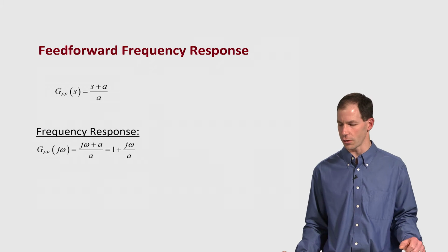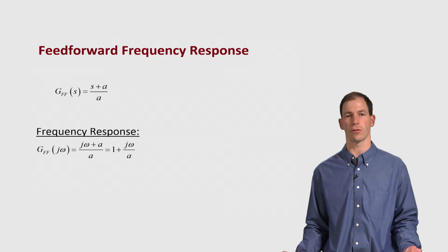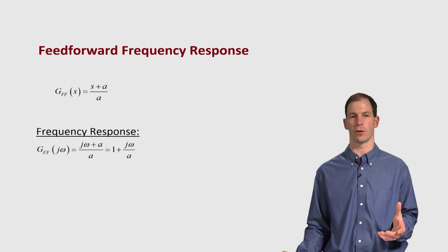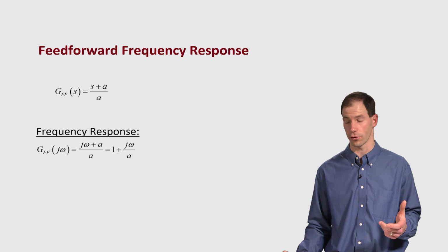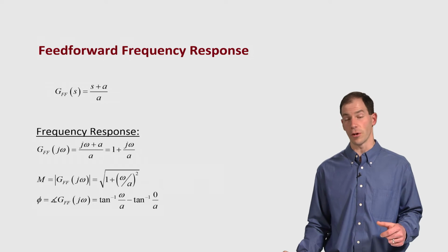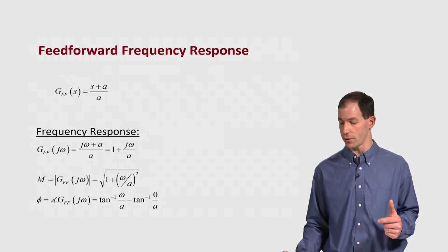Now, let's take a look at how this actually behaves from a frequency response. We already looked at the Bode plot for the closed loop transfer function, or the closed loop plant. Now, let me do the same thing for this feed forward controller.